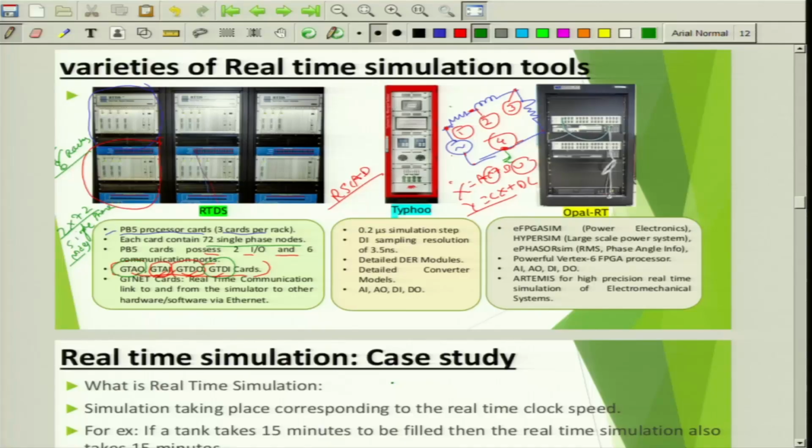Now within the RTDS model, you can have that variable controllable model voltage source, and then you scale down the voltage, because in RTDS whatever the power system model that you develop, the voltage level is in terms of kilovolts by default, and the power level will be in terms of megawatts. It's not in watts or volts. But let's say you have a programmable voltage source of capacity 400 volts.